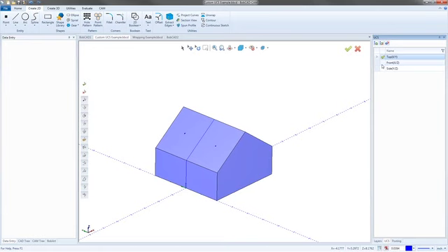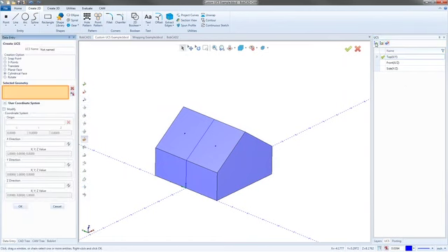It sets up the next function. So what I'm going to do is leave it right here on a top plane for now, and I'm going to right click in this box and say add new UCS. Now you also have this little button right up here that's also to add a new UCS.